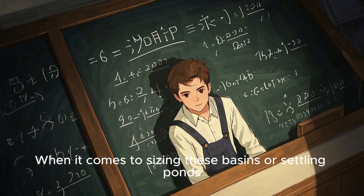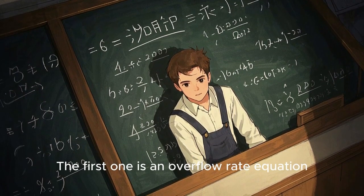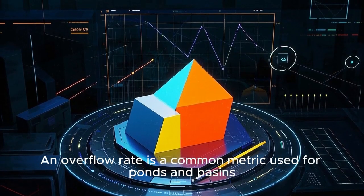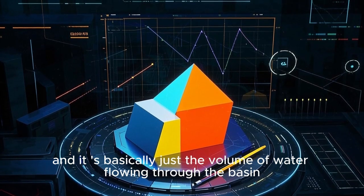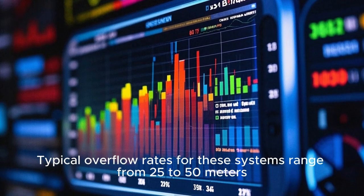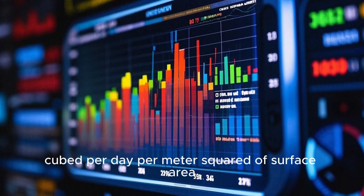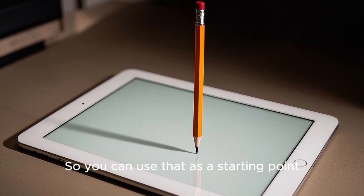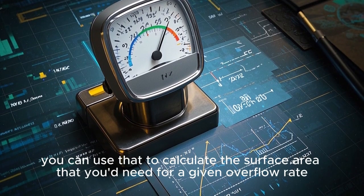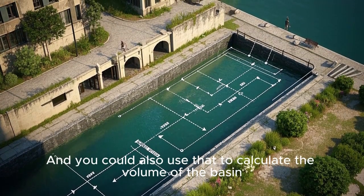When it comes to sizing these basins or settling ponds, there's 2 main equations that we use. The first one is an overflow rate equation. An overflow rate is a common metric used for ponds and basins, and it's basically just the volume of water flowing through the basin divided by the surface area of the basin. Typical overflow rates for these systems range from 25 to 50 meters cubed per day per meter squared of surface area, so you can use that as a starting point. If you know the flow rate coming into your system, you can use that to calculate the surface area that you'd need for a given overflow rate, and you could also use that to calculate the volume of the basin.